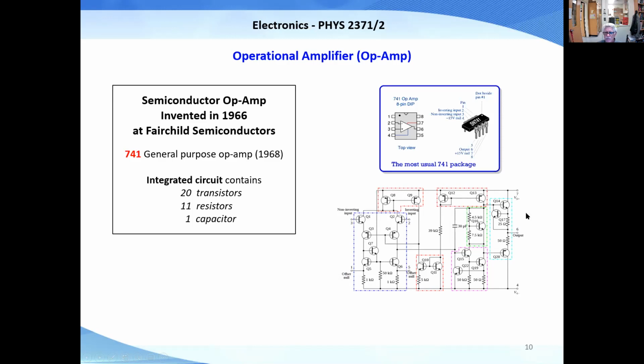One thing about an op-amp is often you want to swing a voltage positive and negative, especially if you have something like audio. You don't need to go from 0 to 10 volts; you can go plus or minus 5 volts, say. So here's the output, and the output can go from the plus supply to the negative supply. In almost all op-amps, you have 2 power supplies, a positive and a negative power supply.